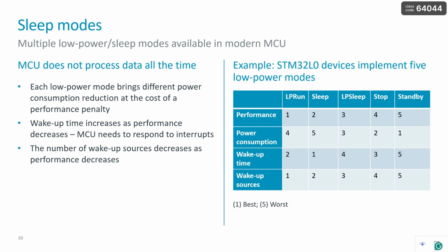Performance is also measured in terms of wake-up times. That is how long it takes an MCU to respond to interrupts when it operates in a particular low power mode. In the example of the STM32 series of MCUs that are based on the ARM Cortex-M architecture, these implement 5 different low power